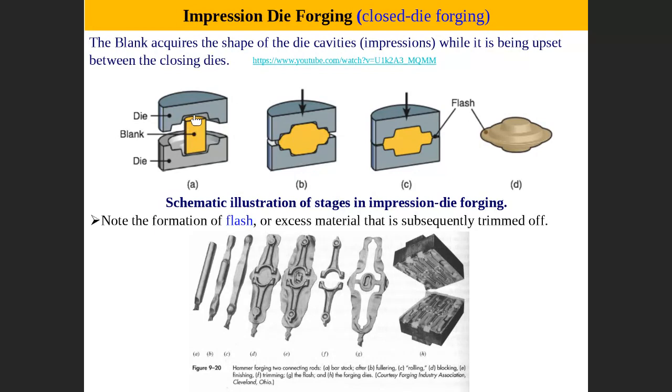Actually, this is a part you put in a heat, you heat it, and when it becomes hot, then you start deforming it. This is the upper die and lower die. This is the workpiece. You apply pressure. When you apply pressure, material will start to deform. Material will fill the cavity, and then part of the material will exit from here and here.